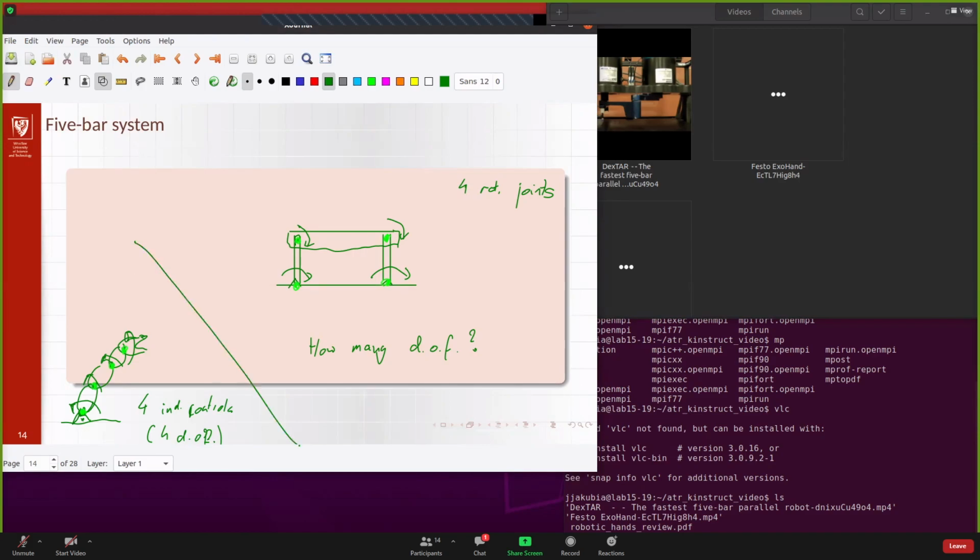Okay, so let's return, and that's typical for serial manipulators. When we have 4 joints, we speak of so-called class 5 joints, joints that can rotate only in one axis. There are other class joints that can have additional movement, but let's assume that those are standard one-axis rotations. So the number of joints is equal to the number of degrees of freedom in the joint space.